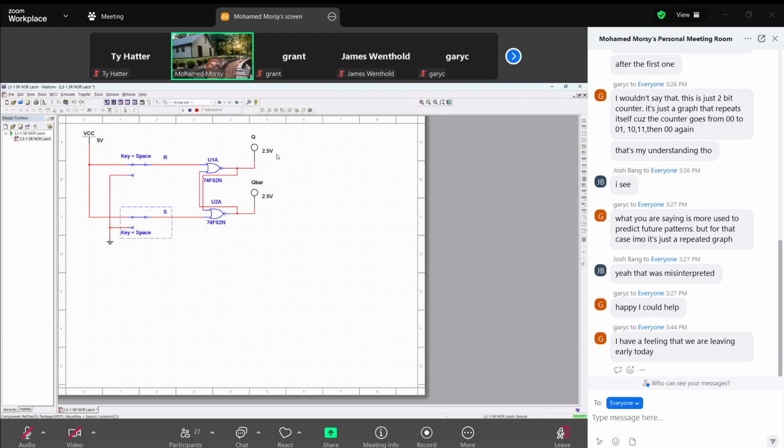So you see 1, 1. What happens for 1, 1? Both of them are off or logic low, which never happened. Because in regular function, as long as Q is 0, Q inverted must be 1. Or Q logic low, Q inverted must be logic high, or vice versa. But we can see here this strange output, which means we don't know the output.